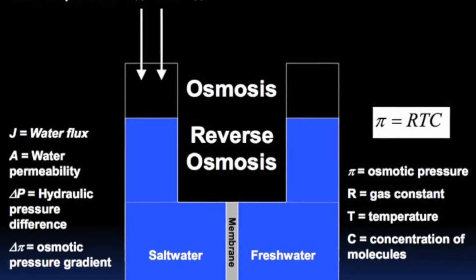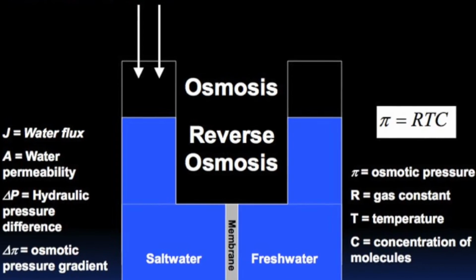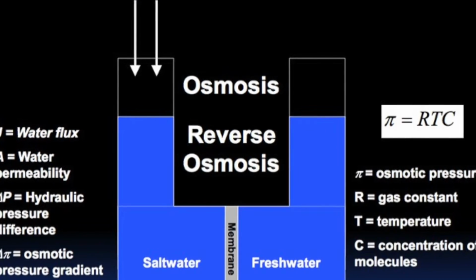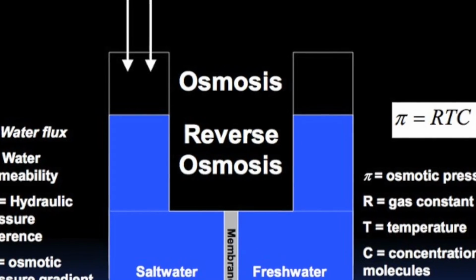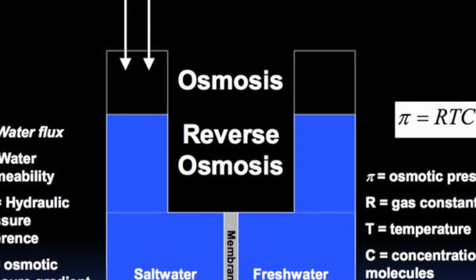Osmotic pressure can be calculated using the Van't Hoff equation shown above. The rate of salt diffusion out of the boundary layer, as dictated by the mass transfer coefficient, is dependent upon fluid flow characteristics within the membrane channel.